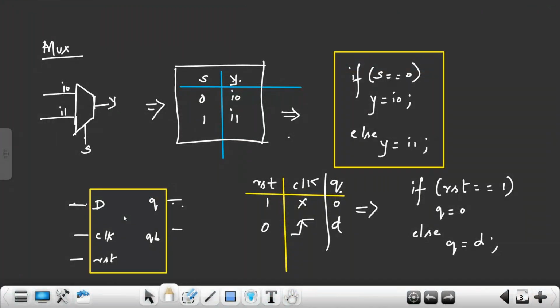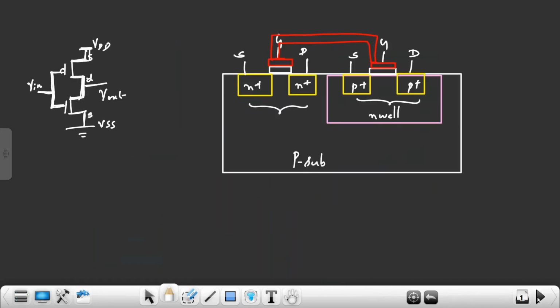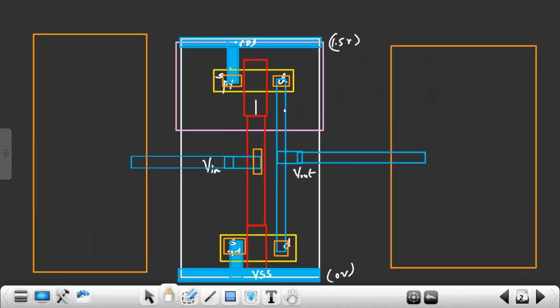Do we see a D flip flop or an inverter directly? You will not see any gates. You will see the layout, the layers. Layout is just an understanding form, in the EDA tool. You will see layers, diffusion. This forms one gate, and one gate connects to another gate using the metal layer. This is what you see in an IC.